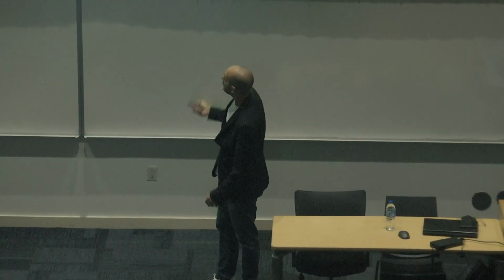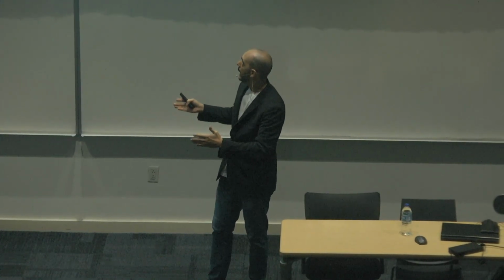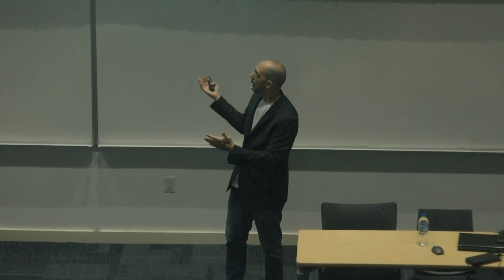So I tried to figure out what was the best way to approach the design using this technology. And what I thought is that, okay, the 3D printing itself basically follows a grid, because we have different layers. Every layer is following a grid of dots. And this reminds me of a modeling strategy that you can use, which is called voxel-based. It's very similar because you have a grid of voxels, meaning volumetric pixels, just small cubes.